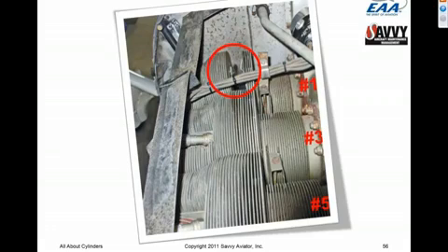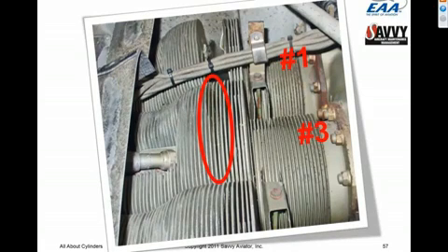It made a forced landing. The mechanic at that little field wound up getting another cylinder and putting it on, and a week later the owner was back in the air continuing his trip, and literally 30 minutes after he took off, he had the number 3 cylinder fail. We went back and looked at the photographs that were taken at the shop that was replacing the number 1 cylinder, and if you look carefully, you'll see that there are exhaust stains between the critical fins on that number 3 cylinder, indicating that cylinder was starting to have a fatigue failure at the head to barrel junction as well, but the mechanic didn't notice it.